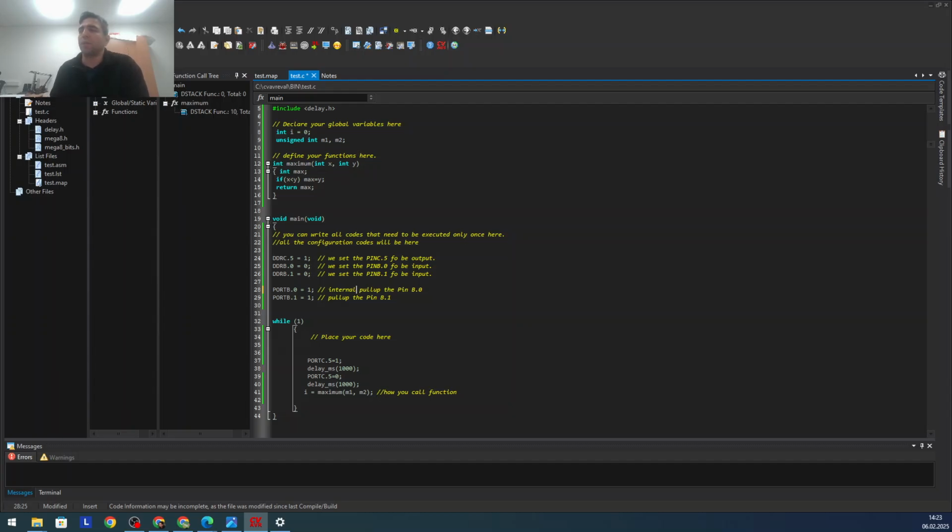Later I will give the code to you also, so you can download it in the model. So this piece of code says I want the internal pull-up to be activated. So when these pins are not connected to anywhere else from outside with the push button or anything else, their value will be 1 in our program, unless they connect to somewhere. Okay.